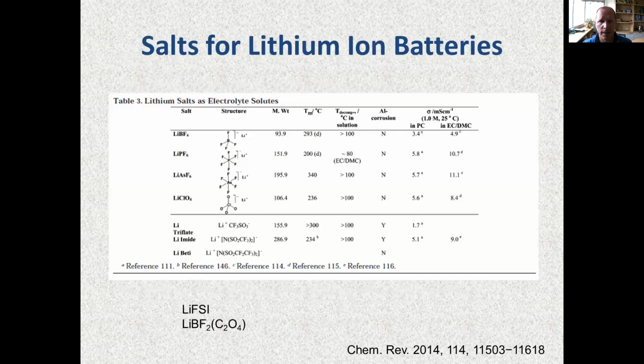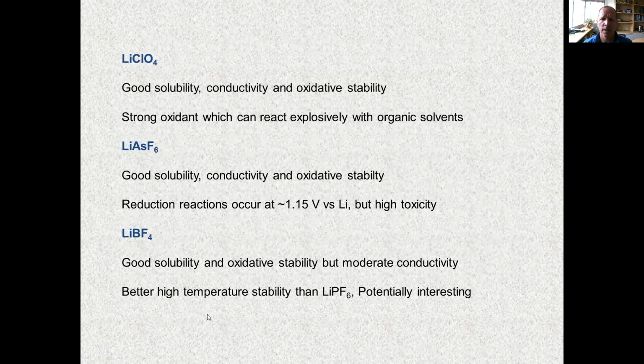It's a little bit lower conductivity than what you see. So we can go back one slide here. A little bit lower conductivity than what you see for LiPF6. Not necessarily prohibitive, but in addition to this, the LiBF4 typically makes a more resistive interface than does LiPF6. So you have two negative aspects with the LiBF4: it has slightly lower conductivity, but it also generates a more resistive interfacial film, SEI, on the anode, which prohibits use in most applications.